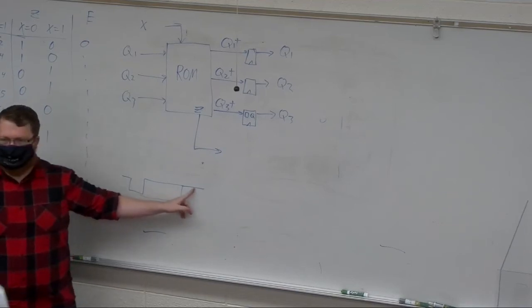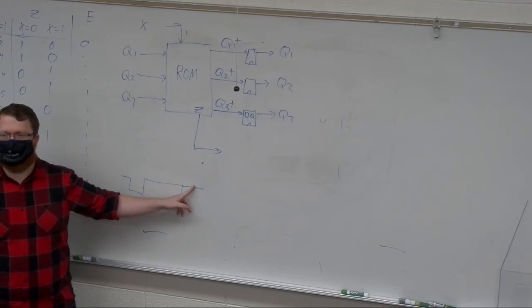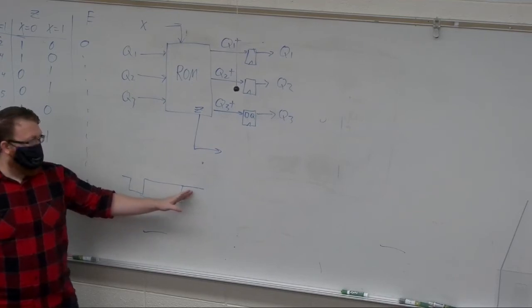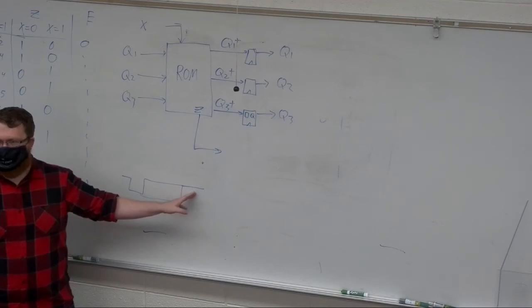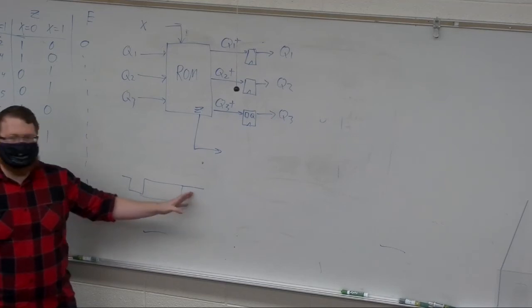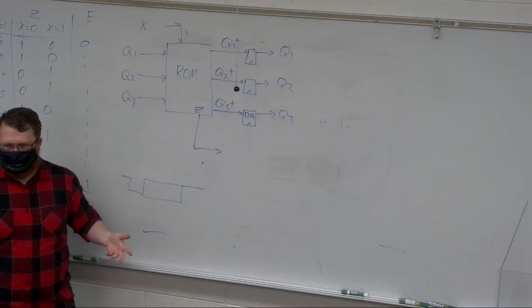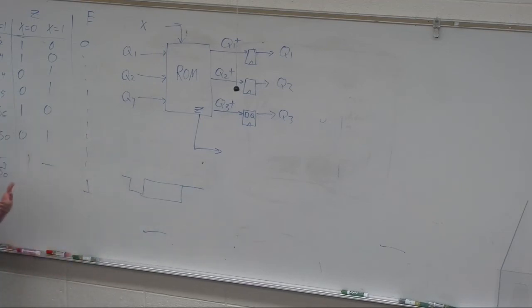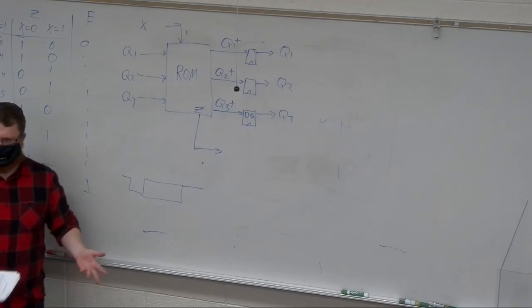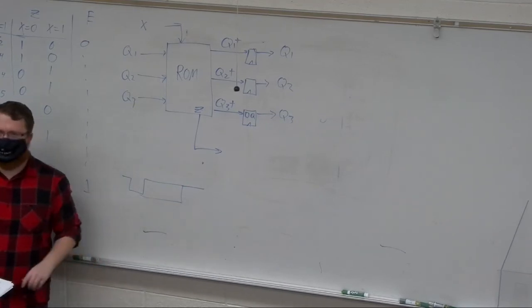It's supposed to go back high for the stop bit. So we can sample the stop bit, make sure it's high. And normally we want to assert ready, saying that we've received all the bits. But if I get to the stop bit, I measure it, and it's 0, I still want to go back to state 0, back to idle. But I don't want to assert ready because it's clearly whatever I just got was garbage.